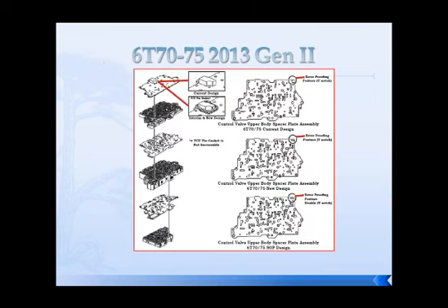Spacer plates had to change to match the TECM. So the channeling in the valve body, channeling in the channel plate area, and of course the oil feed holes through the spacer plate all changed. How you ID which spacer plate you have is pretty simple. Look at the cover in the upper left-hand corner of your display. If you've got that square kind of cover on it, that of course is a first design. If you've got the cover with the gasket on it, that's the second design, so that would be a Gen 2 type of spacer plate.